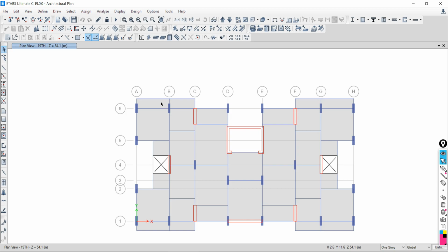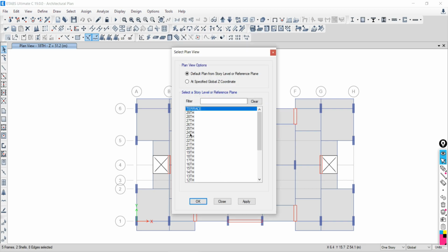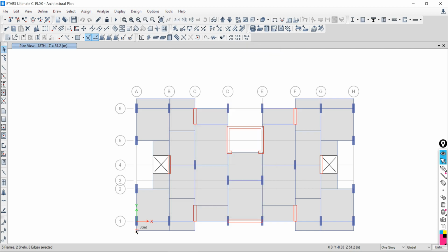Very simple. Just click the frame, then click frame, then click frame, then all the frames. Here I am doing only for 4 to 5. Likewise you have to do it for all the frames, means beams. Then go to shear wall. So it is one floor only. Likewise you have to do it for 29 floors. Is it practicable? No, sir. Then what? Very simple. Just click here, all.